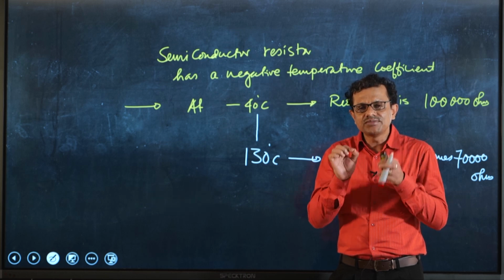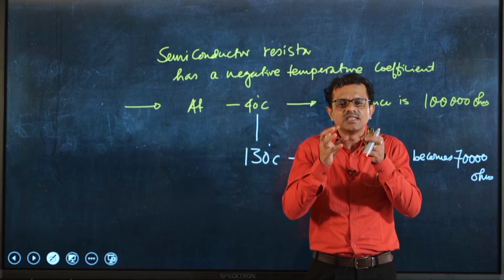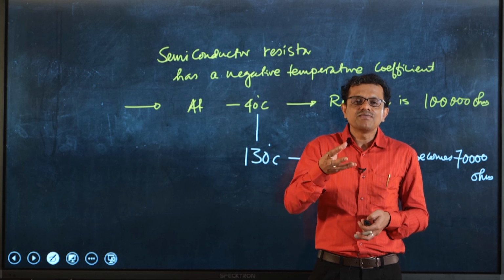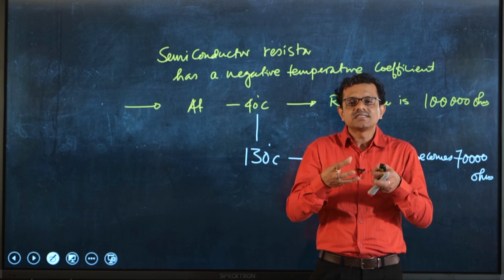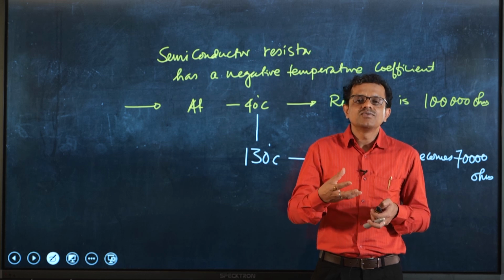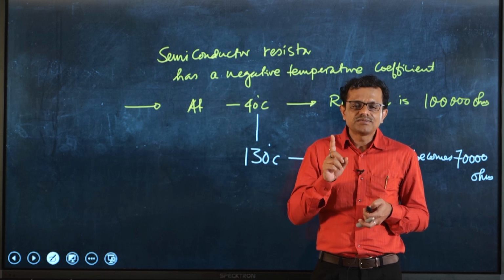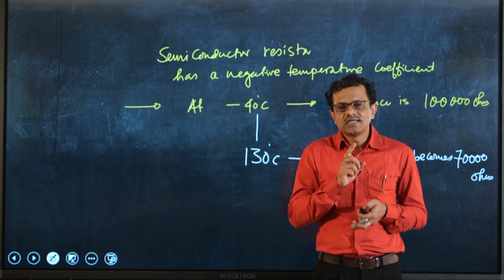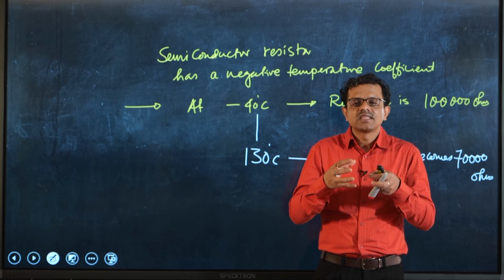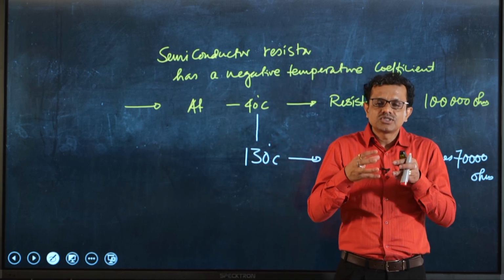If we do not give some information to the fuel injection valve to reduce the fuel sprayed into the engine cylinder, then excess fuel in the absence of adequate air will create additional issues: combustion will not be proper and emission level will increase. So, receiving that signal, the ECU will tell the fuel injection valve to reduce the fuel injection, to match the air and fuel ratio, and it should be the stoichiometric air fuel ratio.